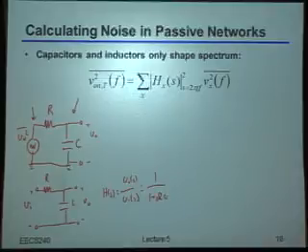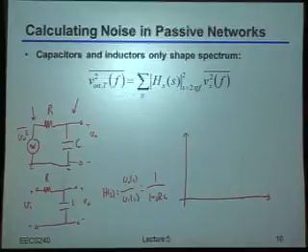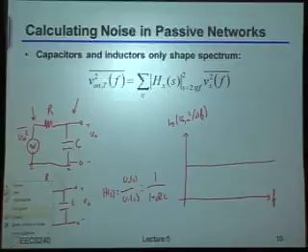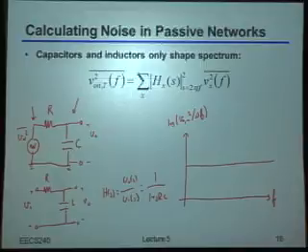So the way this is going to affect us from a noise density standpoint is that if we do a plot versus frequency of the log of the output noise density, then if originally that resistor had so-called white noise, which as a reminder means that it would have looked flat versus frequency, I'll do this in a slightly different color. Once we actually have this capacitor here, what you'll get will be something that obviously looks like a low-pass filter, something like this.